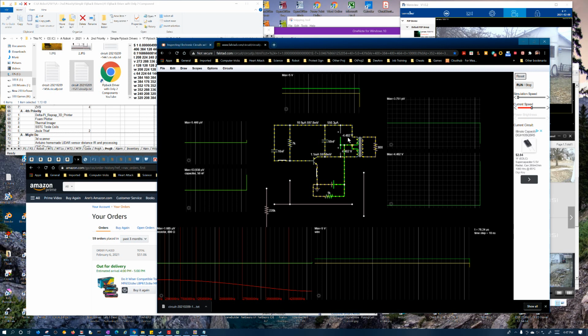Because right now, you can see that initially, this is a 5-volt battery. So initially, our 5 volts comes into the terminal, but it drops down to like 0 volts here, like 500 millivolts, and then 500 millivolts or so here. So this is positive, these two are negative. This is negative because it's going basically through this diode here. And it's assuming still an initial current, which in reality it wouldn't have one.